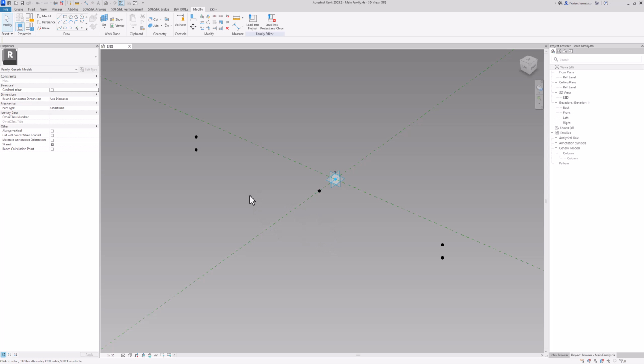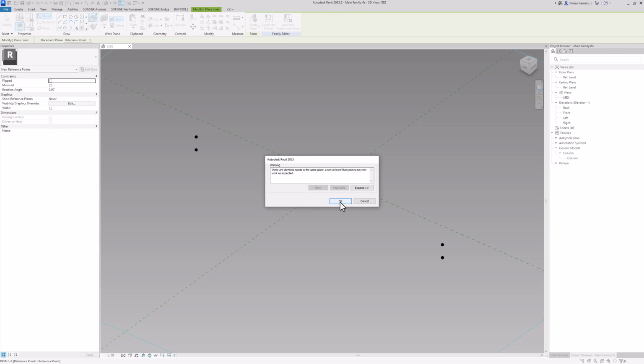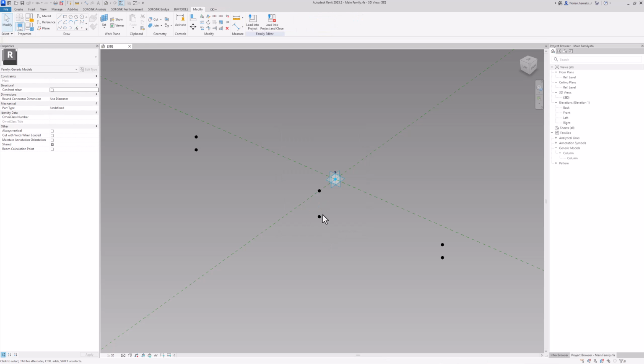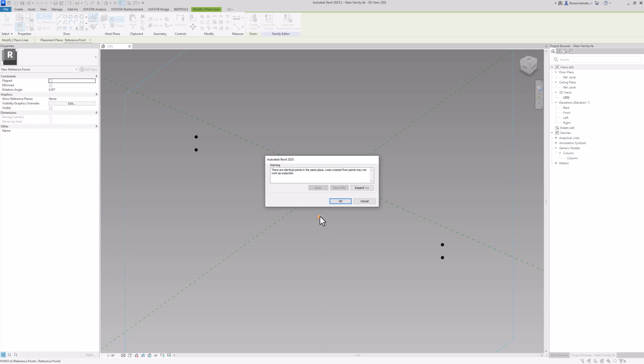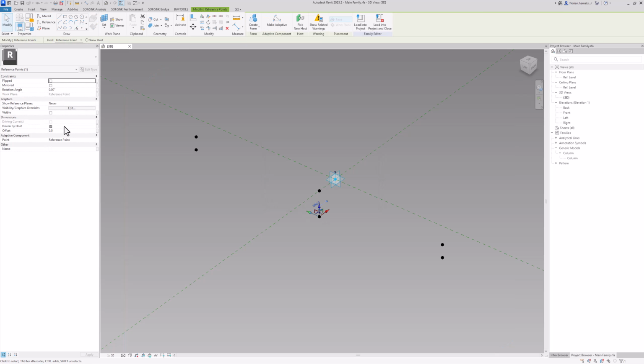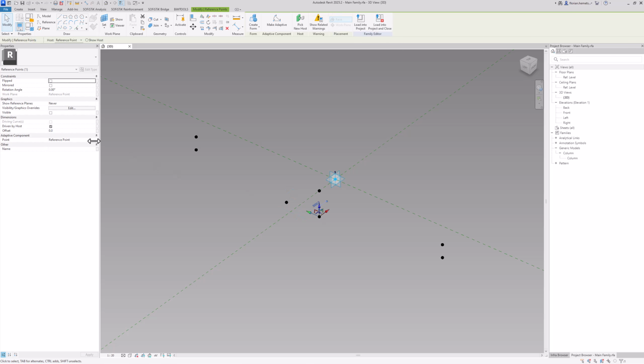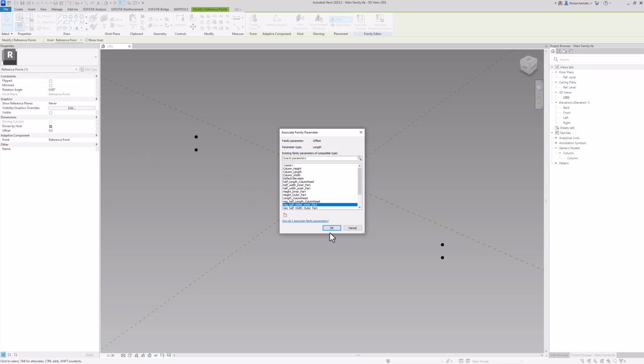Now I want to have the middle of my column head to be referenced. To do so, I want to have one middle point, based on my one offset point that I have here, with a vertical offset, which gets assigned the negative height of my inner part. Based on this one, I can now assign the width of my inner part, and we are as good as done by then. So we need 2 more points in this one. I assign one time the half width of my inner part, which I will find here. And one time I do simply assign the negative half width of my inner part.